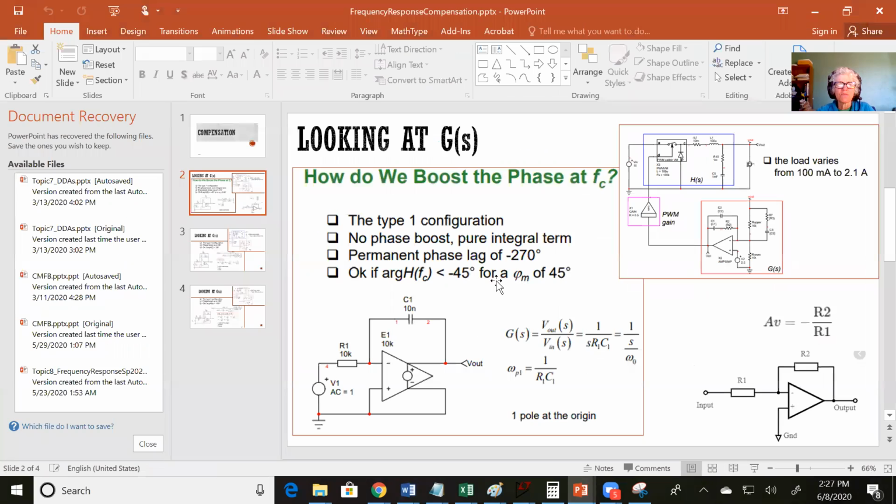Okay, so we talked about a compensation capacitor. Do you remember that? So you have the dominant pole and you have the secondary pole. And if you violate Barkhausen's, in other words, at 180 degrees phase shift, you still have a gain of greater than 0 dB. Hopefully that sounds familiar. Yeah. Okay, so that capacitor is to move the dominant pole over, so your gain drops below 0 dB.